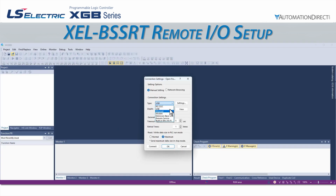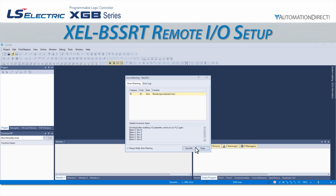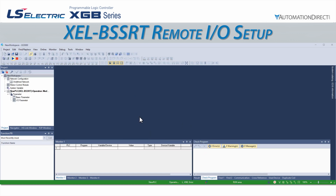We are going to use USB for our connection, as it is quicker than trying to move our computer to the same subnet as the controller to connect. We will use the Open from PLC option. Select USB under the type field, and then click OK. We get a module type mismatch error because we have our 5 modules physically connected to the BSSRT, but the default program from the factory contains no modules in it. We will close this warning for now. Our first step will be to rectify that.